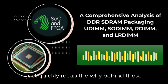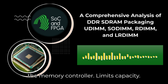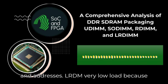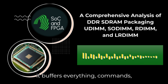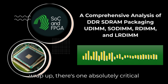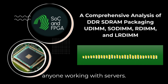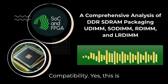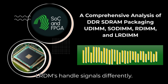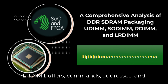And if we just quickly recap the why behind those choices, looking at that electrical load again. Sure, UDIMM: high load on the memory controller, limits capacity. RDIMM: low load because it buffers commands and addresses. LRDIMM: very low load because it buffers everything, commands, addresses, and data, allowing the highest density. Perfect summary. Now, before we wrap up, there's one absolutely critical warning we need to give, especially for anyone working with servers: compatibility. Yes, this is non-negotiable because RDIMMs and LRDIMMs handle signals differently. Remember, RDIMM buffers commands and addresses, LRDIMM buffers commands, addresses, and data.